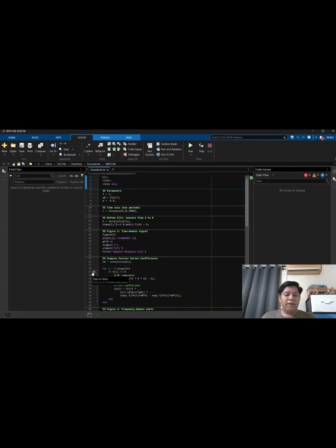On line 29 until 31, this is the DC analysis, where we calculate the average value of the signal over one period, which is 3.42 in this case. And then on line 32 until 37, for all other values of k we apply the Fourier series integral. This specific method converts the rectangular shape of the pulse into complex numbers that represent its frequency content.